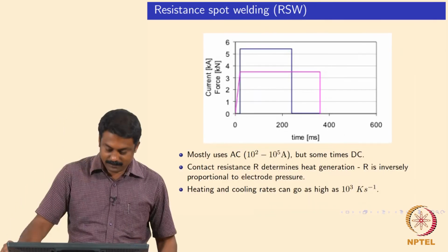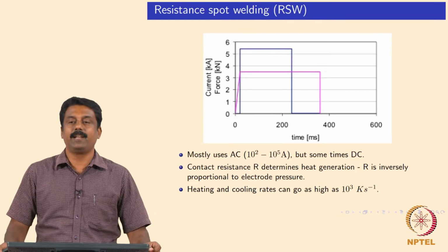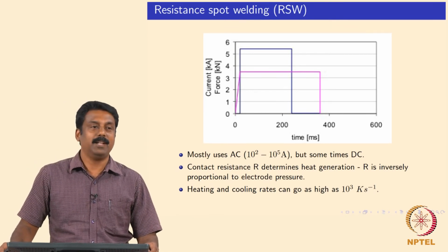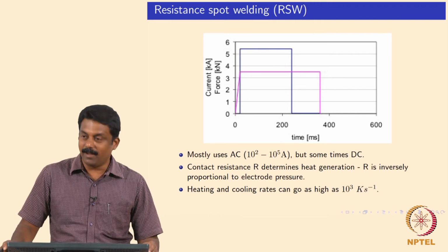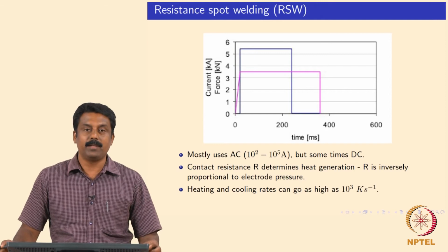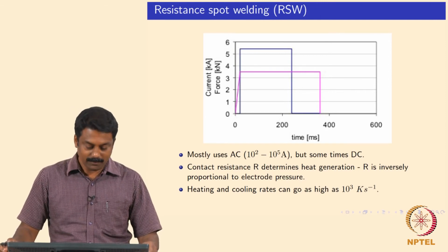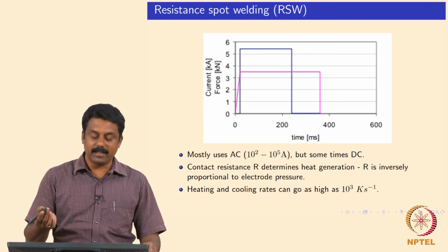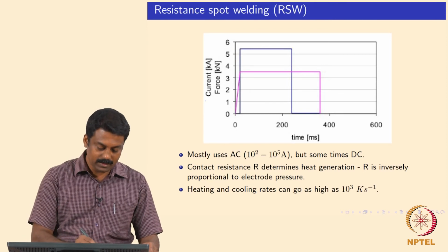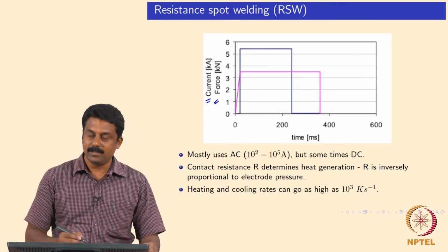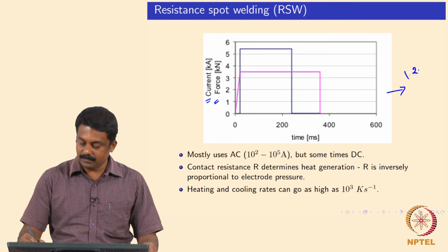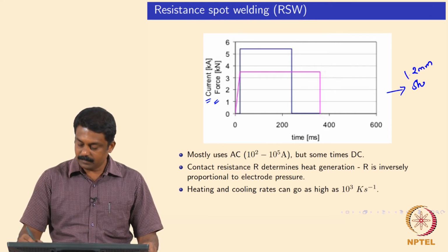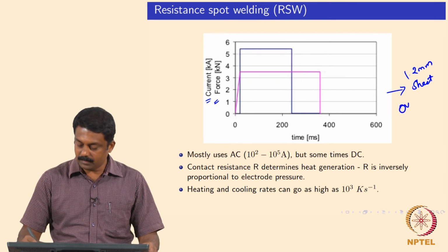Good. So, this is a typical weld thermal cycle we follow. What is a weld thermal cycle? It is because we always need heat, right? We pass a current and simultaneously we also apply some load. In a conventional resistance spot weld thermal cycle, you have current versus force. Generally, we have such curves. This is done for a 1.2 mm sheet in overlap configuration.